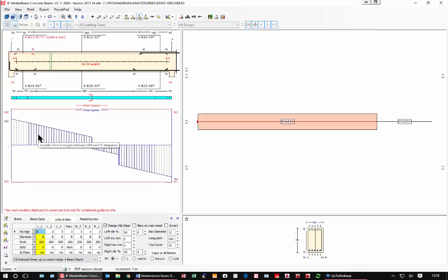So those are the old-fashioned rules that are in the BS and also in the Eurocode. So we're taking it and we're curtailing it up to there. That's great. In this case we don't need to, actually, because it's well in with that third leg on the breadth of the section. We possibly could have got away with the 300 being less than 3 links.